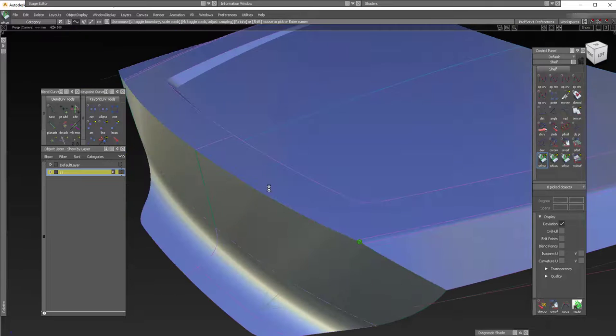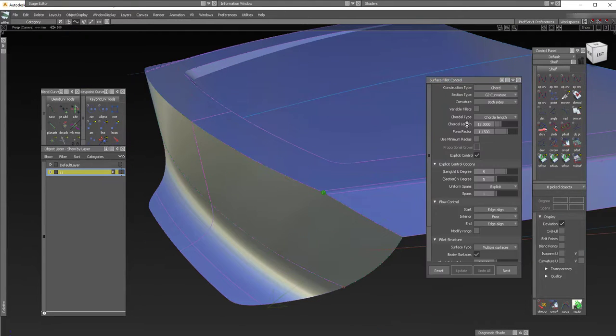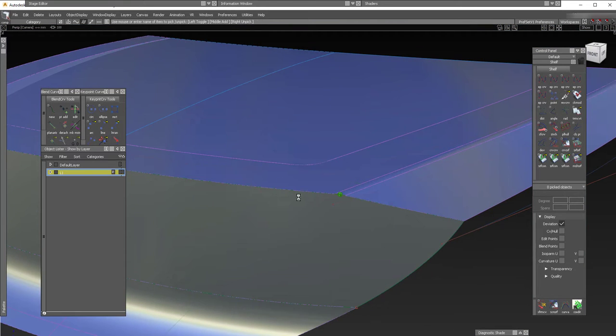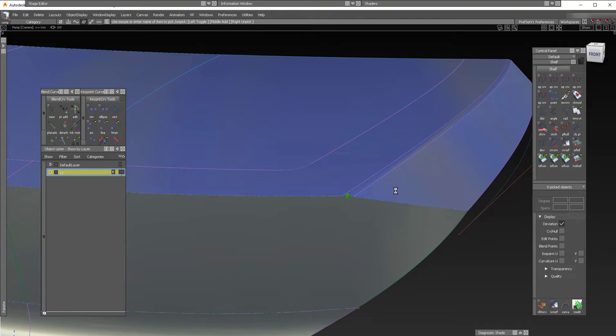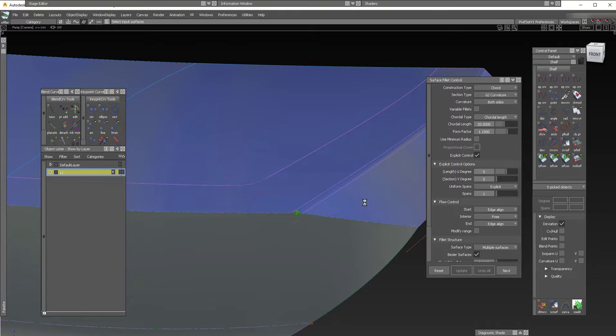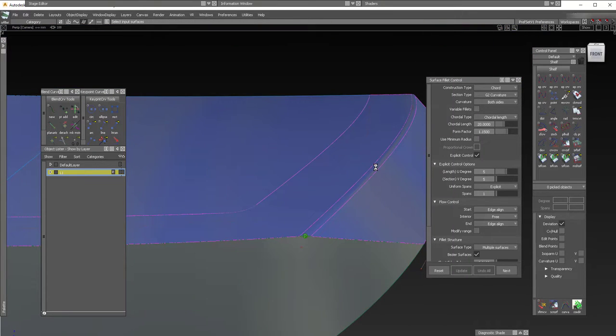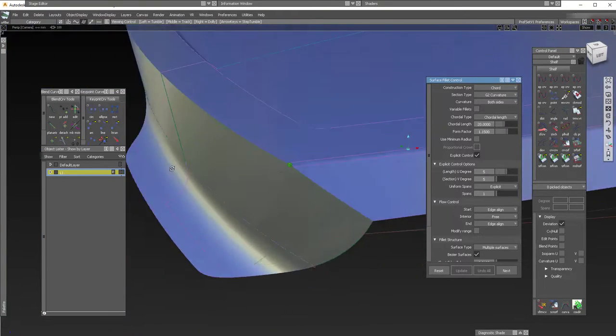Okay, let's give it a fillet here right now. 20. About filleting, I did this small fillet before this one because when you pick multiple surfaces at the same time while using the fillet tool, there needs to be at least tangency to select these surfaces.